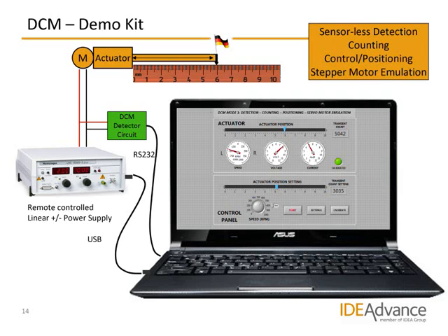The controller program picks up the counting pulses from the detector and uses them in a control loop to control the linear power supply. With this kit, we can set an actuator position and demonstrate that the actual actuator moves to the set actuator position both forward and backwards. We can also adjust all motor and control parameters in the system to account for different motor types.